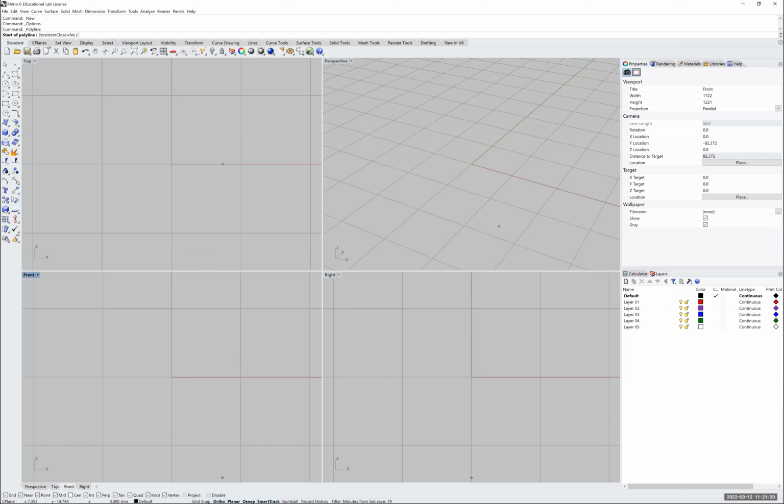If it's turned on, I can always turn it off, and so I can have more access or more variety of angles to draw my objects. Following that, I'm going to skip the planner and go to OSnap, which is the snap to object, which is what I'm going to be using. Because this is turned on, you can see that these options at the top are also turned on, and those are the OSnap objects.